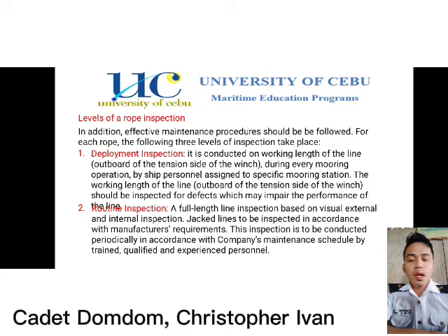The working length of the line, or outboard of the tension side of the winch, should be inspected for defects which may impair the performance of the line. Second is the routine inspection. A full-length inspection based on a visual external and internal inspection. Jack lines to be inspected in accordance with manufacturer's requirements. This inspection is to be conducted periodically in accordance with the company maintenance schedule by trained, qualified, and experienced personnel.